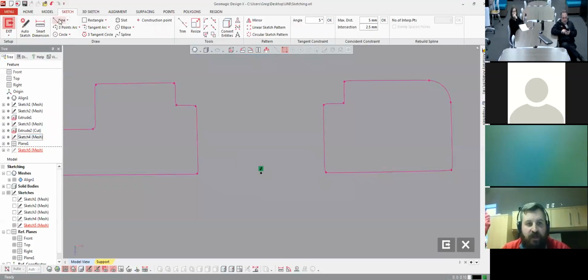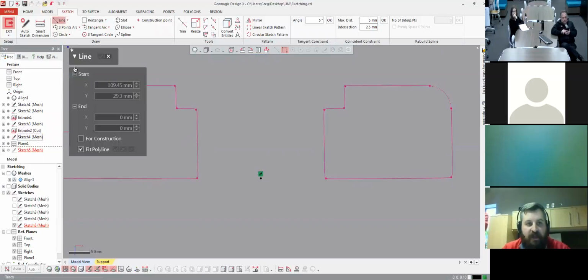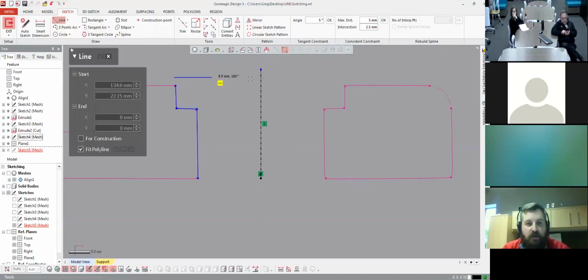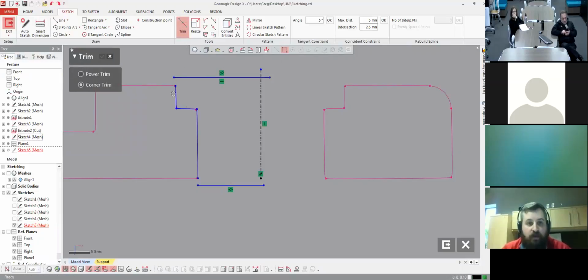So now I can draw central axes, a construction line, and I can build my actual sketch. I can quickly do what I was talking about earlier. I can quickly snap some lines there, and I can trim those out. I'm just going to create a little bit of a reference slightly bigger than the geometry itself. This makes sure it intersects past that geometry, so when I do this revolve cut, everything is put in the right place. There's nothing line on line.